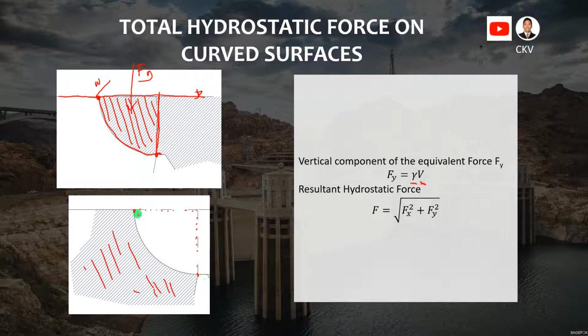If this is not filled with fluid, our equivalent vertical force here is going upward. Again, to compute F of y, we still apply the unit weight times the volume above the curved surface. So the volume that we are still going to use here is the same, this volume right here.